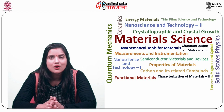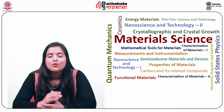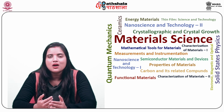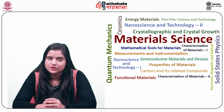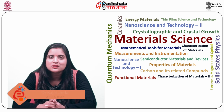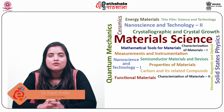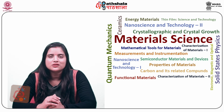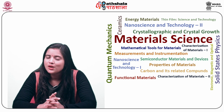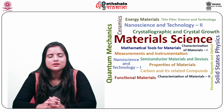Four-point measurement for resistivity calculation was carried out on a thick film with and without edge boundary conditions. Also, the 2-probe method was discussed and compared with the 4-probe method. Finally, the van der Pauw method to determine the resistance of a uniform sample was also described in detail. Thank you students for your attention.